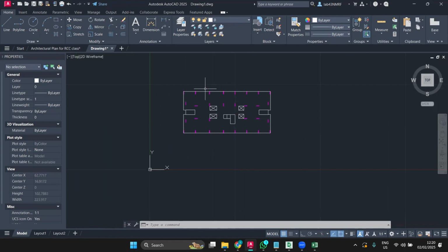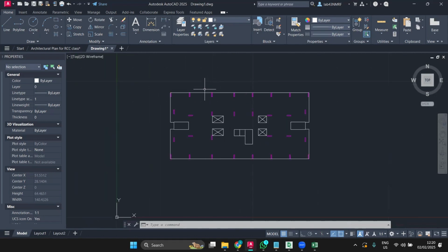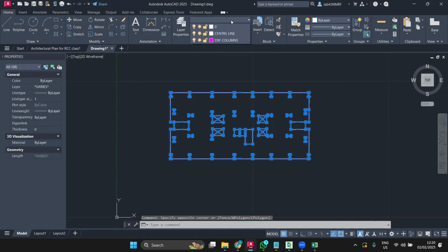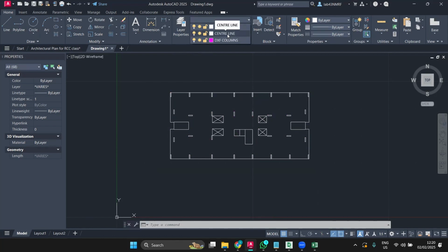This is the typical flow, the one which we did for the typical flow. The good thing is that you place the columns, you arrange the columns, you calculated the columns. Very good, right? Check how many layers are there. Select everything, make sure it is in one layer. It has to be in one layer.